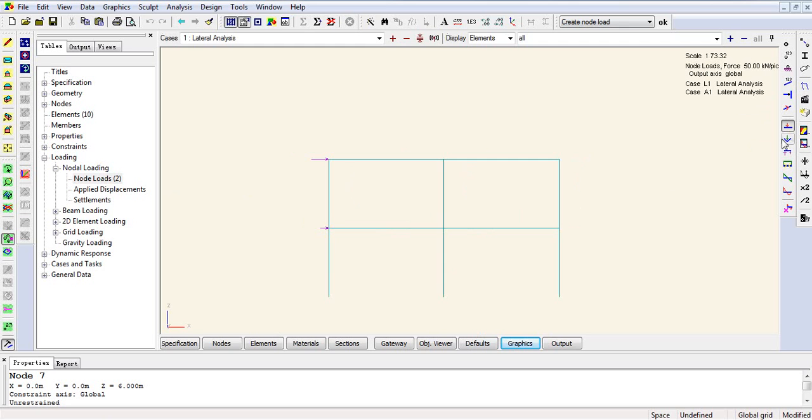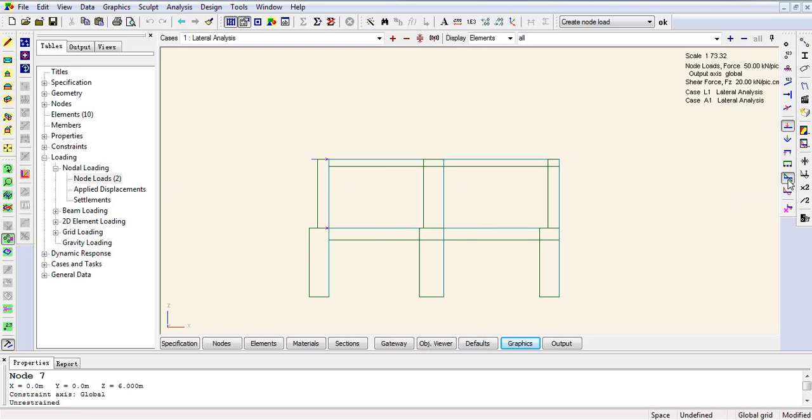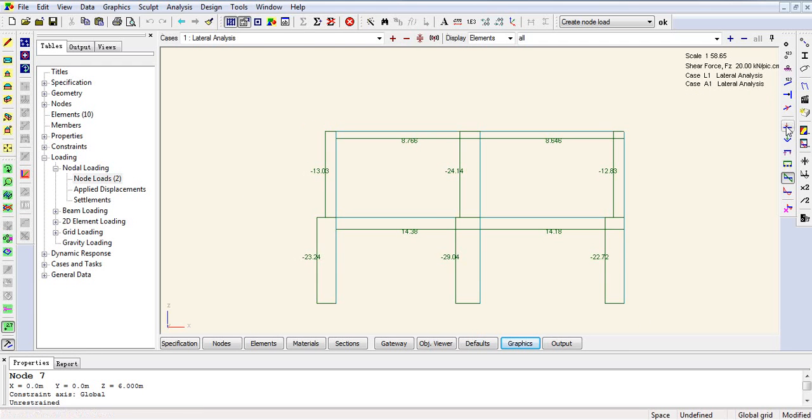Then we can see the shear diagrams, which is the FZ shear force diagram. So you can see the shear force of each element. Our view is actual value. We can select for animation and select them all, and close the loads. We can see what the values are.